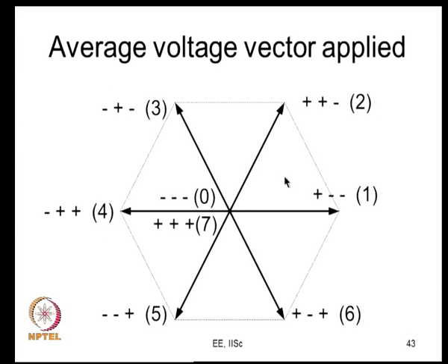So, if I look at the voltage vectors, what happens now? I might come to slightly higher modulation indices. Like this. You can very evidently see that if I call this Vref 1 and I call this Vref 4, their magnitudes are very different.